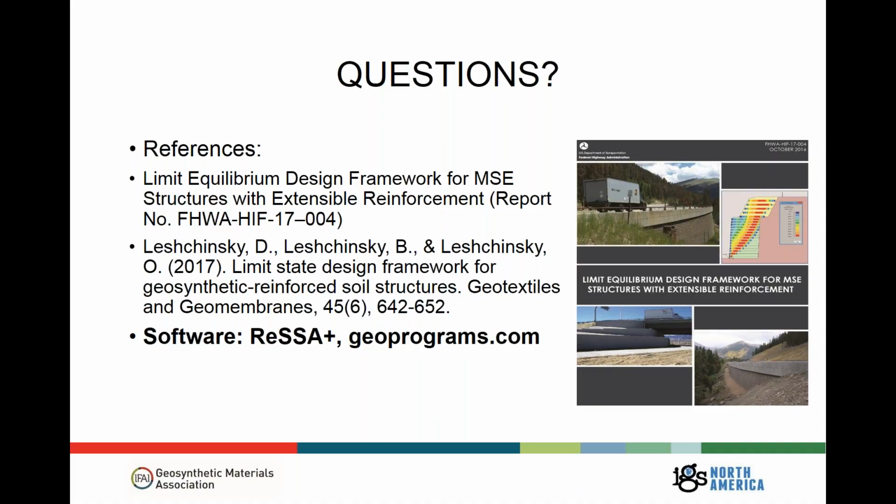But in a 3D approach, since we have this three-dimensional geometry and these boundary forces acting on a three-dimensional failure surface, there's more resistance in the soil, so the reinforcement loads will decrease. However, an interesting paper just came out this past year that shows that since the mechanism changes, the failure surface basically deepens.